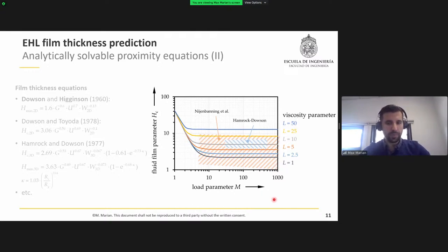And to describe non-dimensional groups and parameters or the film thickness equations, basically they can deliver quite reasonable agreement with many lubricants that was experimentally verified by the British authors, for example, by interferometric film thickness measurements. However, there could be some deviations under certain conditions due to fluid compressibility, thermal effects, or shear thinning, starvation, or also surface roughness. And all these aspects have not been fully considered in the original numerical solutions based upon which these kind of approximation equations were derived.